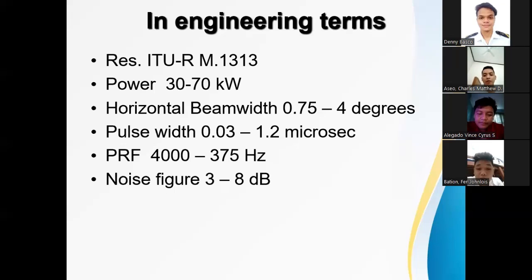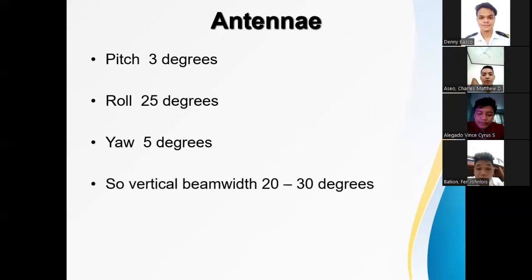PRF 4000 to 375 Hz. Noise figure 3 to 8 dB. Pitch 3 degrees. Roll 25 degrees. Yaw 5 degrees. Vertical beam width 20 to 30 degrees.